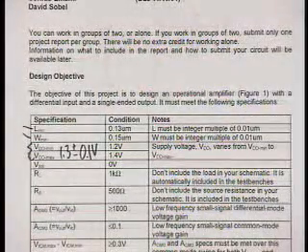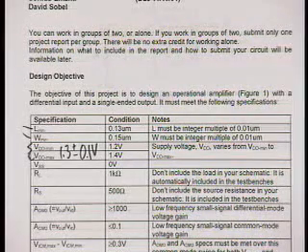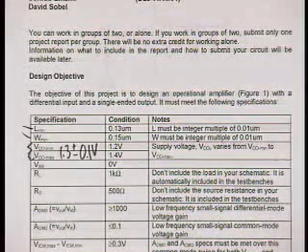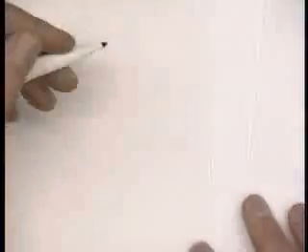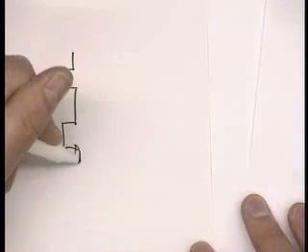And the reason we're doing this is twofold. One is because in actuality, when you're out there designing circuits, supply voltages will actually vary. You can't guarantee an exact voltage for a whole host of reasons. So you want your circuit to be robust over a range of supplies. Okay, so that's one thing. And the other thing, and I think I mentioned this last week in section, is that a lot of times in class or on your design project 1, people generated bias circuits by doing things like this.